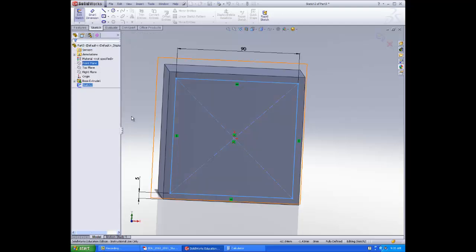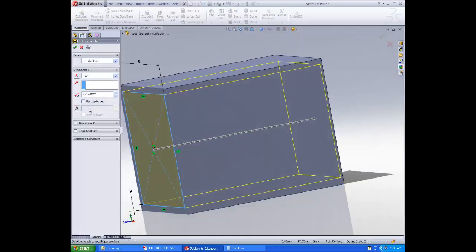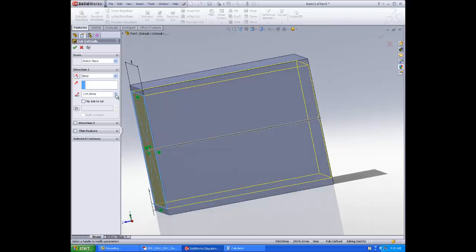and we selected the wrong thing. So select your sketch, go to features, and extrude the cut. Do an extrude cut. Now this is not going to go through all. And because it's going to be a centimeter gap, we need to let's set it to 114.